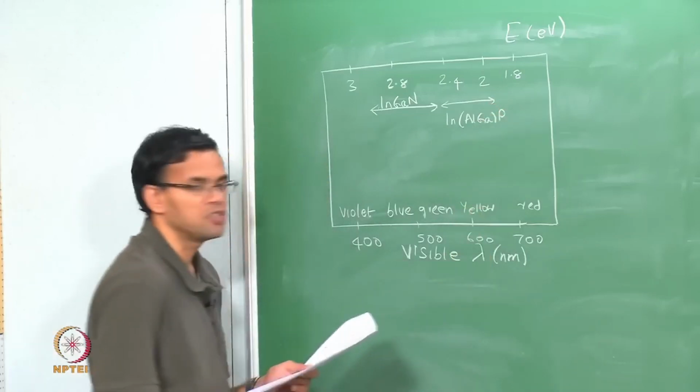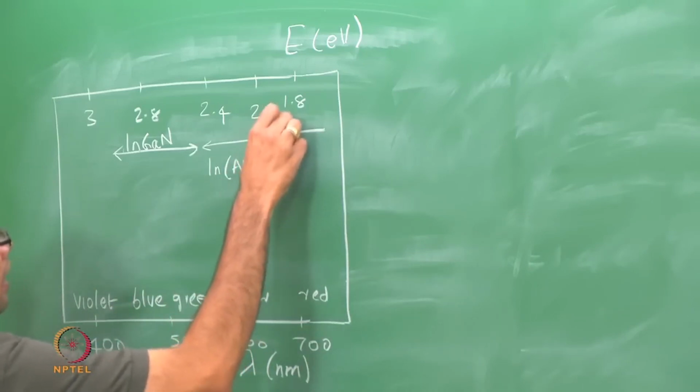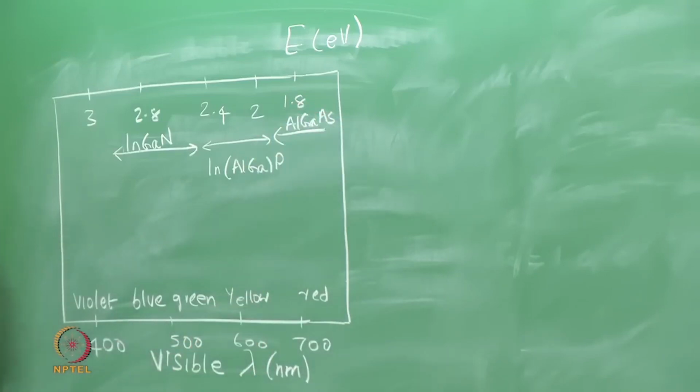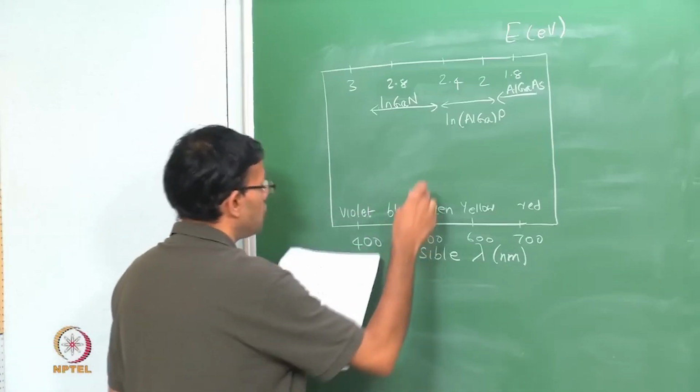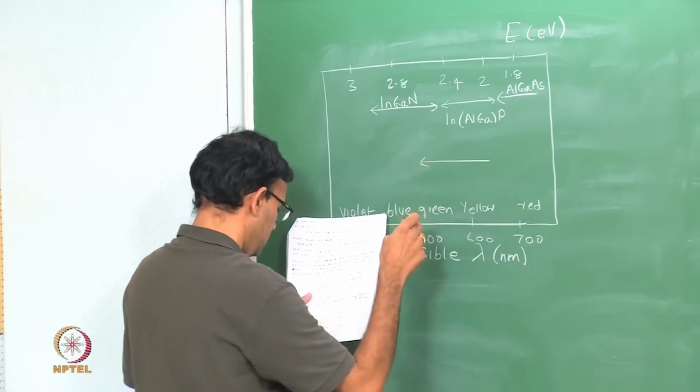So it's an indium phosphide doped with aluminum and gallium. We already saw AlGaAs that has an energy around 2 electron volts depending upon the value of x. You also have gallium phosphide based materials.